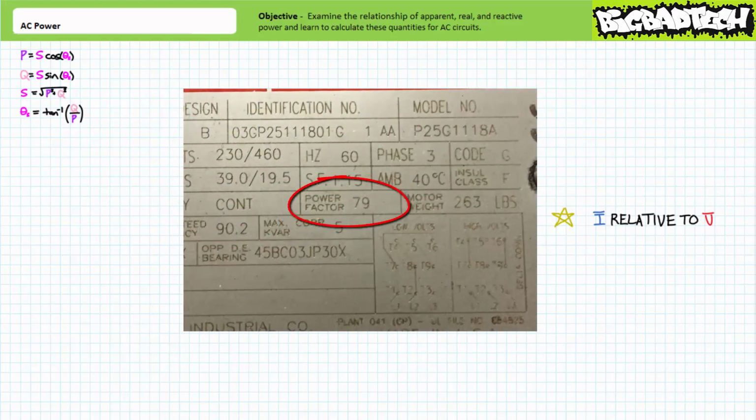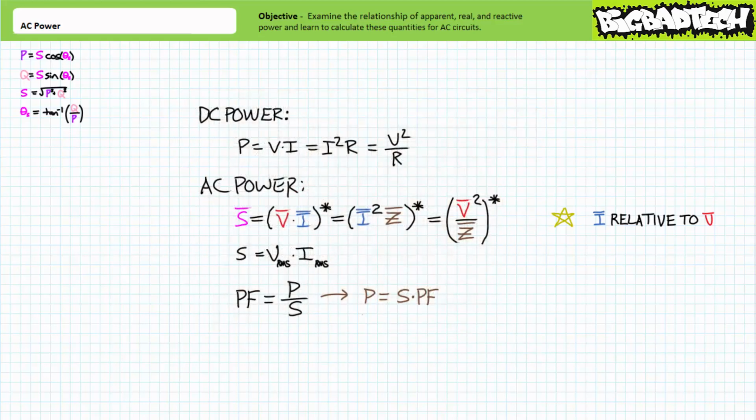Power factor is something often directly stamped on a motor nameplate. A drone will be dispatched to take 2 measurements, a voltage reading and a current reading. Multiply the voltage times the current to get apparent power. Multiply apparent power times power factor to get real power. Record the values, move on to the next task, and repeat. Despite the crudeness of these old school techniques, you can't help but admire their efficiency. It's for this reason alone that I cannot honestly say that I'm entirely new school. On occasions when I just need a single piece of data, I'll just old school it to get what I need as quickly and painlessly as possible and move on to the next problem.